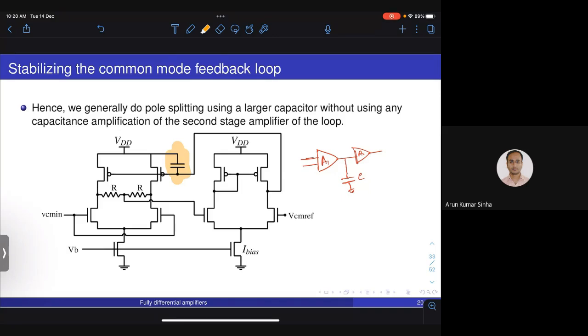So we have now looked at how to stabilize. How to detect a common mode without affecting the gain, we will look at that now. And actually, we are using this feedback op-amp to solve the mismatch problem, right? Yes. What if this feedback op-amp is also mismatched? It doesn't matter.